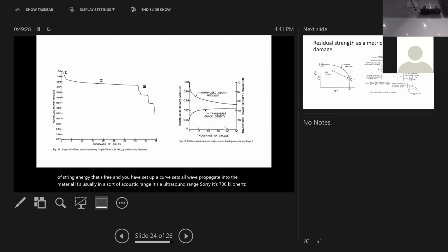You can measure it if you use a sensor which is sensitive enough, like a piezoelectric sensor stuck to the surface, and that sensor picks up this little burst of energy. You can actually count how many times it occurs. You can classify this signal and associate some with fiber breaking. And then you can stick that sensor on the material forever and just record the occurrence of these things over time. And then you can possibly detect the burst events.